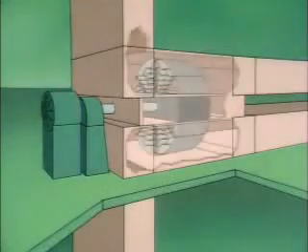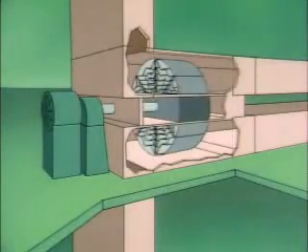In some boilers, the air supplied to the combustion area is preheated. Preheating the air raises its temperature closer to the point where ignition occurs. This, in turn, helps to ensure efficient and complete combustion. One way to heat the air flowing into a boiler is with a rotary air heater or preheater.